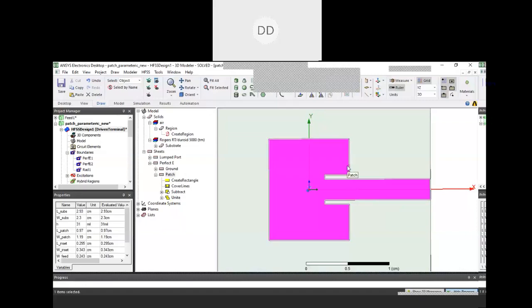Second, do an analytical study of the patch antenna, the rectangular microstrip patch antenna with the ground on the other side, and generate an equivalent circuit of that. Then add them together, put them together. Directly taking whatever equivalent circuit any software gives you will not be accepted unless you give a reason why that equivalent circuit is there.